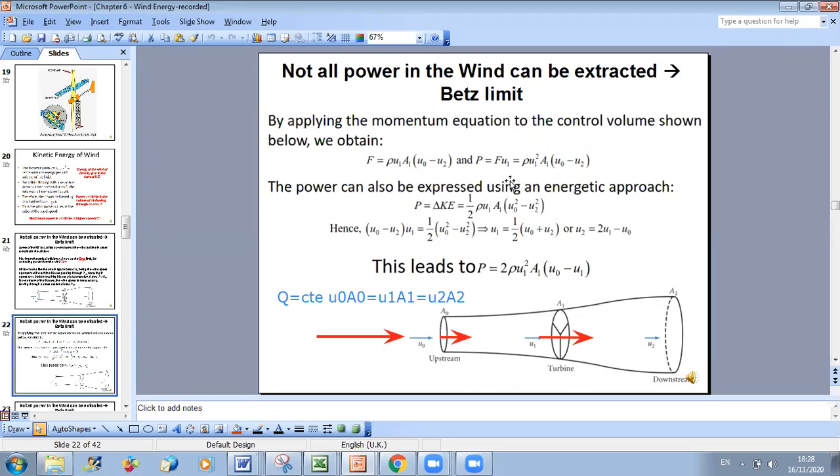So we can write that the power that we will extract through the turbine is equal to the force F on the turbine times U1, which is the velocity of the air going through the blades. Now, how to calculate the force F? The force F can be given by the following relation, which is called linear momentum. As I told you, I don't expect you to know these relations, but for some, it might be interesting. This is why I am explaining it.